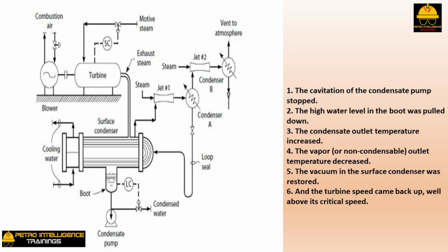As none of the other water coolers in the plant had been affected, he concluded that the cooling water inlet to his surface condenser was partly plugged. He had the front end plate on the cooling water side of the surface condenser, called the channel head cover, removed. Most of the tube inlets in the channel head tube sheet were plugged with crayfish. The offending wildlife were removed. The condenser was reassembled. The motive steam was started to the turbine.